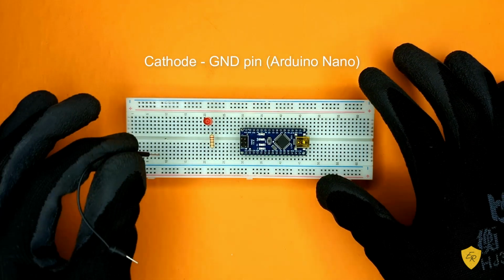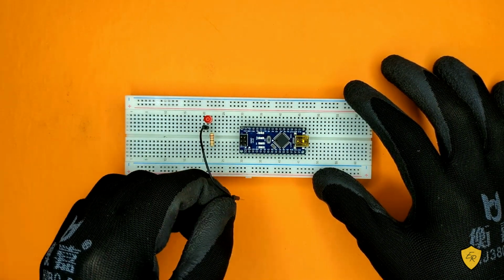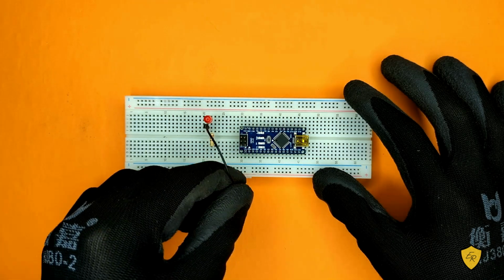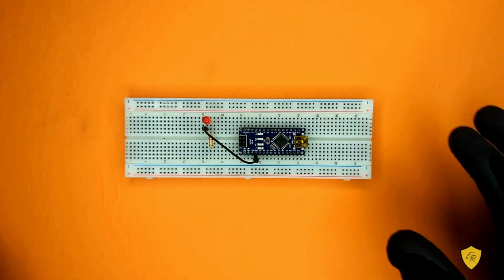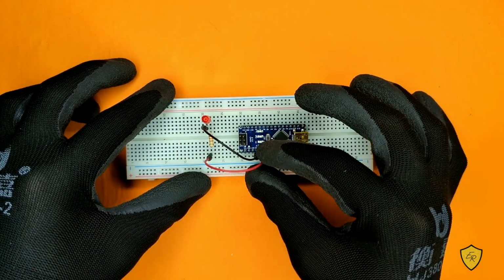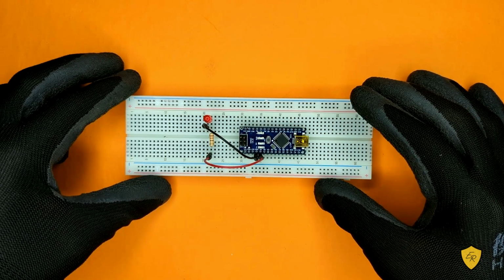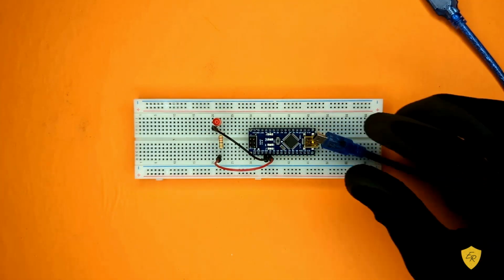Then the cathode of the LED goes to the ground pin of the Arduino Nano. Now the anode through the resistor is connected to D2 of the Arduino Nano. Connect the cable to the microcontroller in the PC.